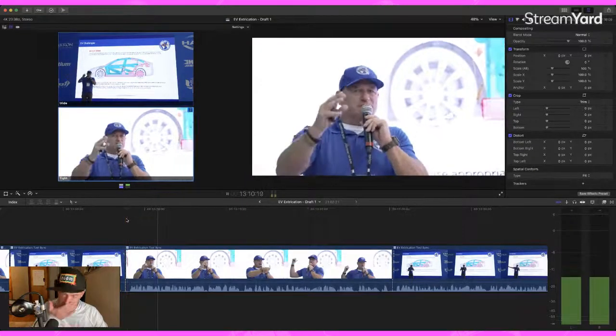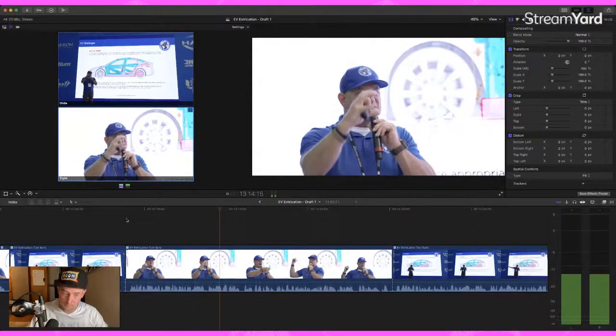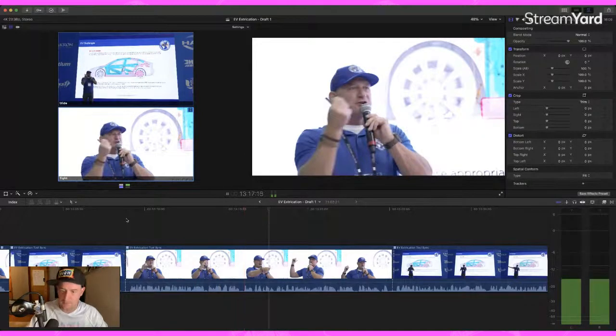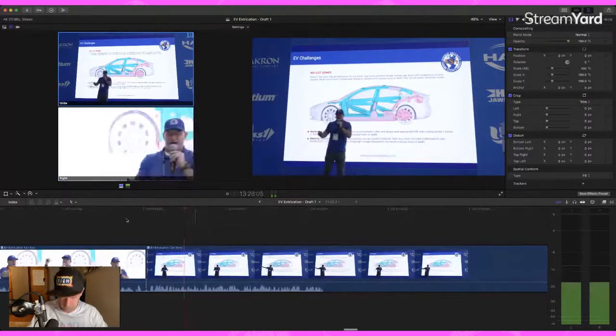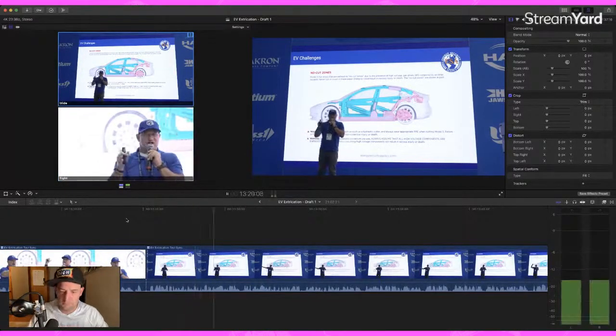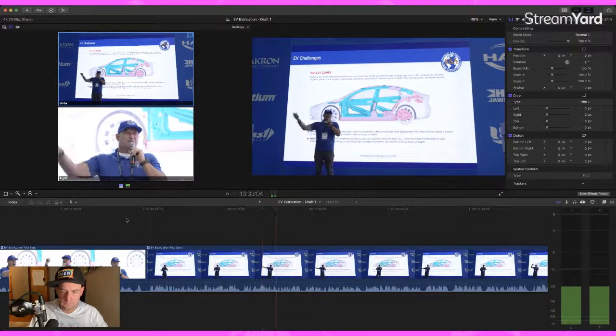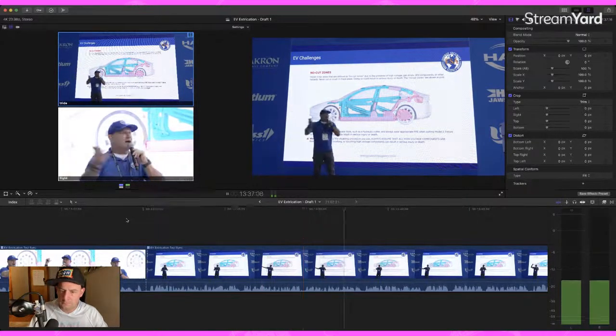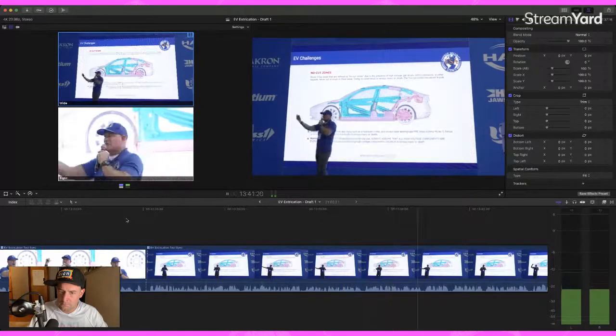Many of the vehicles will have what, for lack of a better term, we'll call a generator that is designed to pull energy from heat or active braking. When we're doing shutdown procedures, the extrication special starts with ignition interactions and power buttons, and then if necessary, your next step should typically be a 12 volt. If you want to try not to cut cables, you want to try and remove cables. So if you need to re-engage 12 volt power to gain control over the transmission, you have that availability.